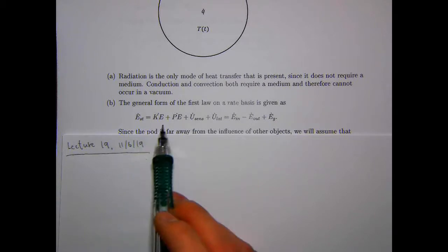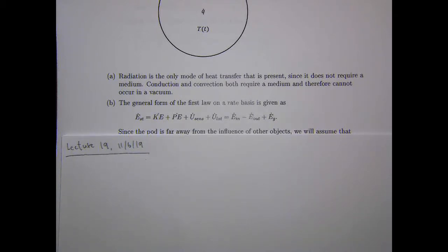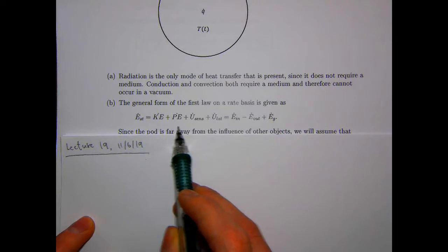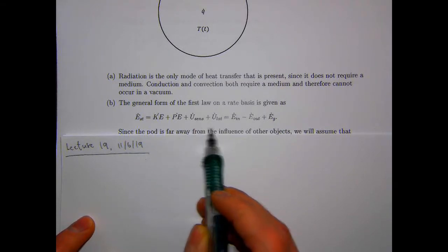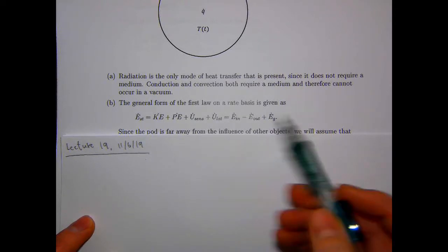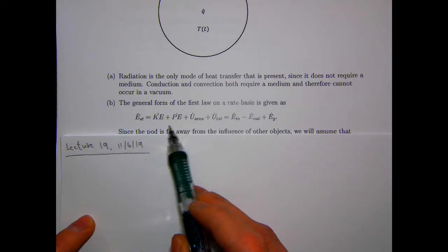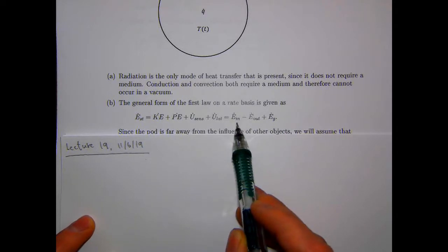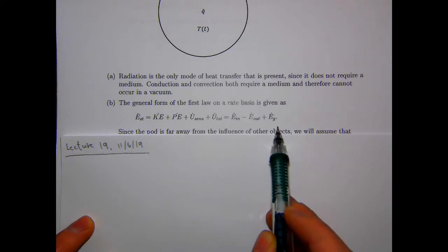That can be many different types of energy: mechanical, potential, internal. For heat transfer, we consider mechanical, so kinetic and potential energy, and then thermal, sensible and latent. And the rate of change of stored energy is equal to the energy that is moving in or out of the control volume plus the energy that's generated internal to the control volume.